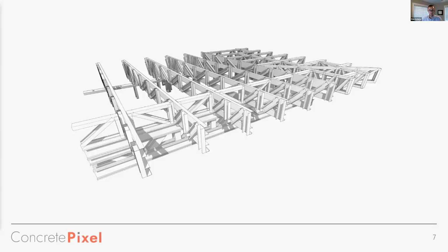So the example here is a two-way cantilever truss condition. Even complex situations such as this can be carefully thought out and designed in a controlled environment. By designing trusses in place with the BIM model, there's a high amount of efficiency thanks to real-time feedback against the architecture model. Things like fascia depths, overhangs, slope, etc. So uncommon and unique conditions can be vetted to ensure problems during installation are minimized.